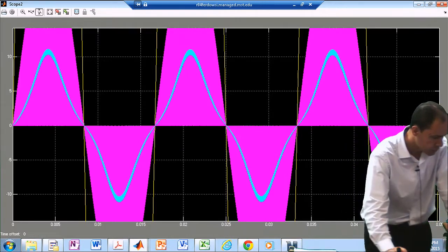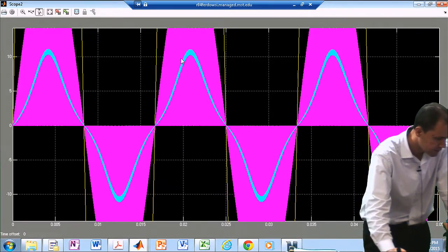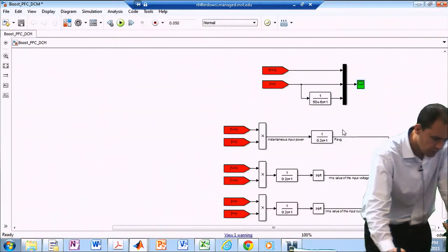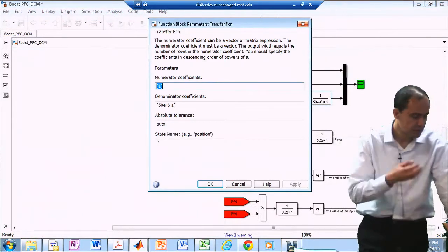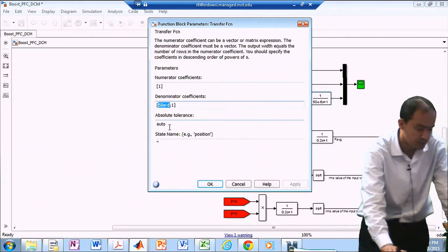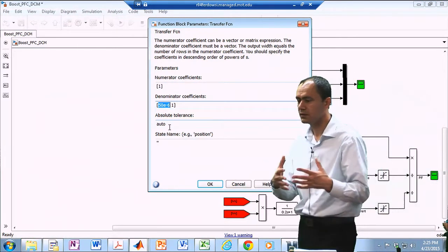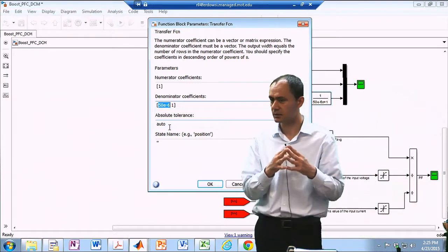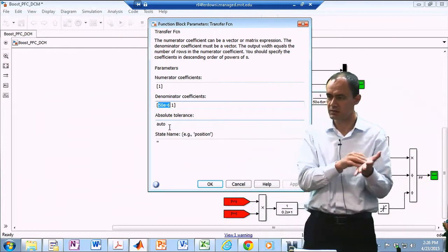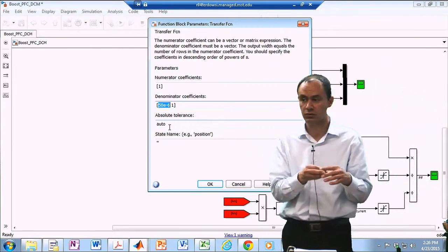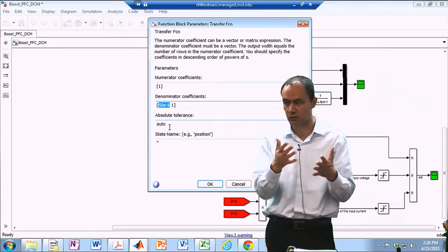One thing that I can show to you guys is, we don't really have to zoom in here. It's just a low-pass filter. But see how small this number is over here. It's like 50 micro. That means the filter that I'm using is just trying to eliminate the switching frequency ripple. So if you really want to implement this filter on the input side, the capacitors or the inductors that you need to use are relatively small because they are trying to eliminate 100 kilohertz.